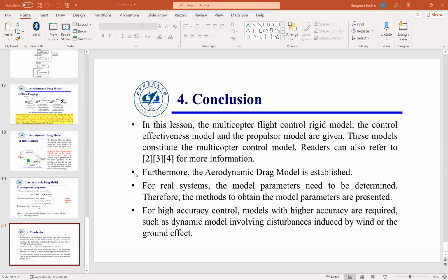So here we don't have a quadcopter. What we have is a fixed wing aircraft. However, the coordinate frame is exactly the same. We have the Earth-centered, Earth-fixed coordinate frame, and we have a north, east, and down coordinate frame. North axis is U, down axis is W, and east axis is V. And you have P, Q, and R. Those are the angular rates. Please understand, theta is the pitch angle, phi is the roll angle, psi is the heading angle.